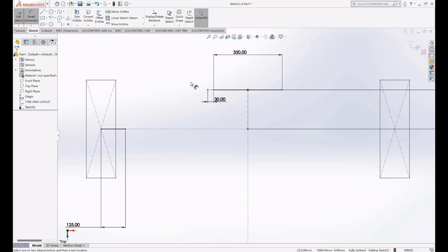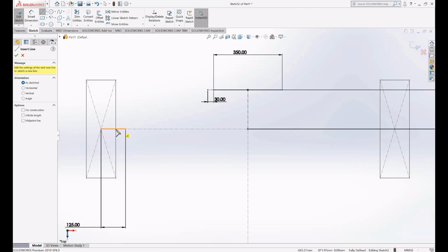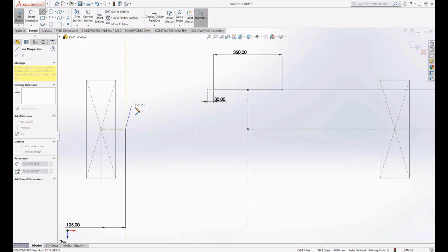The center is where the rack connects to the steering rod. Now we need to have a steering arm. So this is the spindle, and in the top view your steering arm will be directed towards the vehicle, which is this side. So you make a line like that.